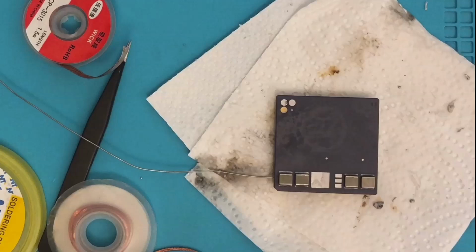If you use normal diodes, its drop is around 0.7 volts. Then Schottky diodes maybe 0.3. So with Schottky it might be possible to get nice steps, but you would have to place a lot of them. And this time this should be fairly large to handle the current. So either way, yeah, I don't like this diode solution.